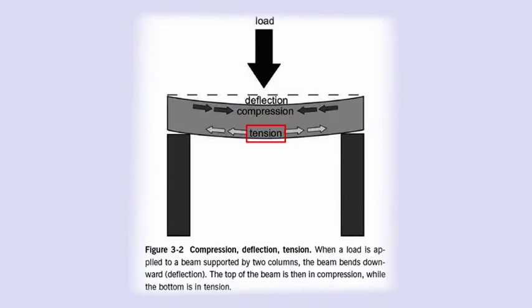Tension is the reaction of a material to stresses, stretching or pulling on a material along the direction of its length. A beam that bends and deflects is subject to an internal combination of compression and tensile stresses. Interestingly, the material that lies between the compressed and stretched areas is subject to relatively little stress. This is why steel beams, for example, can be designed with a wide top and bottom and a narrow middle.